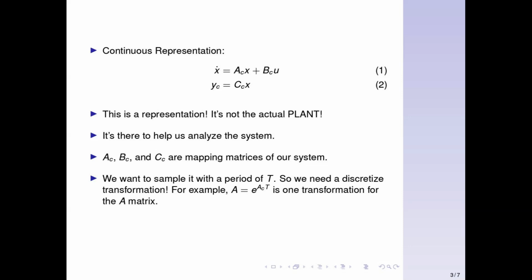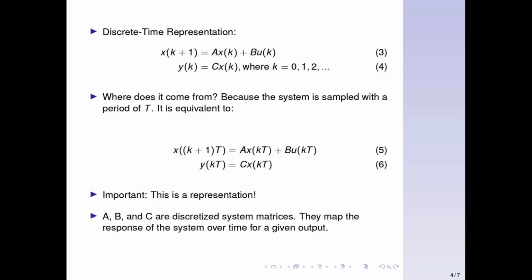Now envision having a continuous system operating seamlessly, and your goal is to comprehend and control it within a digital realm. Through discretization, you break it down step by step, much like frames in a movie. The matrices A, B, and C become your trusted tools in facilitating this transition. A discrete sampled data system could be a robot, an aircraft, or even a financial model.